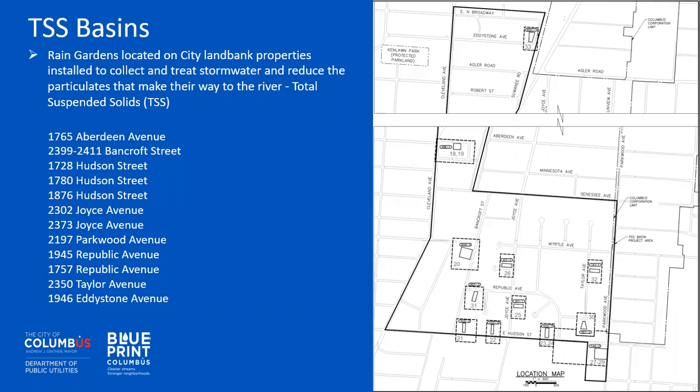So while I let that linger up there, I'll give an explanation why we're calling it the TSS basins. TSS is actually an acronym for Total Suspended Solids, which is basically the gravel and dirt and any particulate matter within the roadway that is carried by stormwater to these basins. We use total suspended solids as a proxy for total pollutants that are occurring from what we call non-point source runoff.